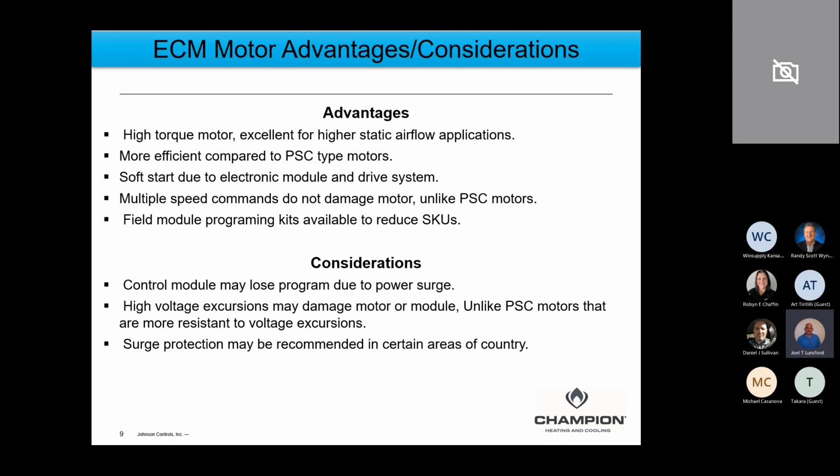They're more efficient compared to a PSC type blower, because as I said, it's a 3-phase type of motor that's actually driven by a module on back that converts single-phase power to 3-phase power. You're also going to have a soft start on these motors due to the electronic module and the drive system. So unlike a PSC blower, where when you just start the thing, you just have line voltage going to that winding, and it just kicks right off pretty quickly.